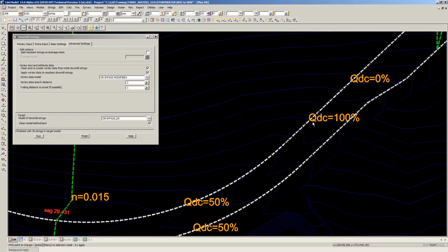Now this is by the time the contours have turned around a bit and a channel starts to form in the gutter here. Before you get to this point, the water that's making its way down the catchment here as the contours are turning around, that's all sheet flow and it's barely worth modelling. But having the reach starting up there and set to 0, at least the flow rates are accumulating there. So the flow rates gradually build up along these overland flow strings, the catchment flow rates.